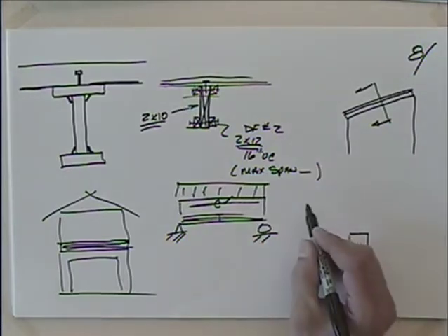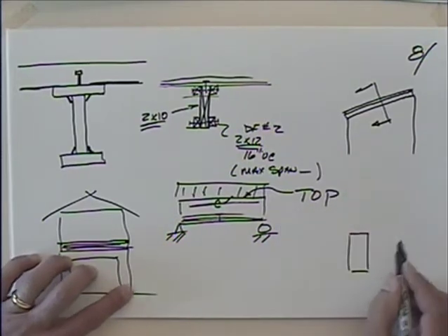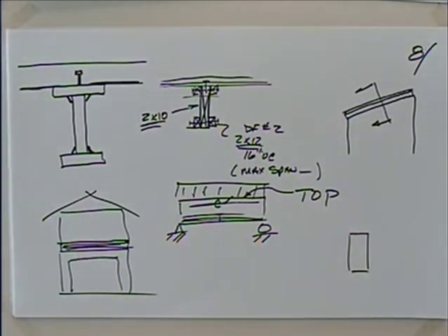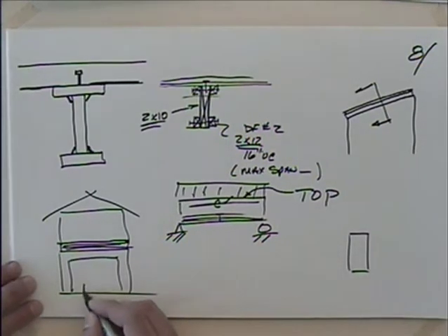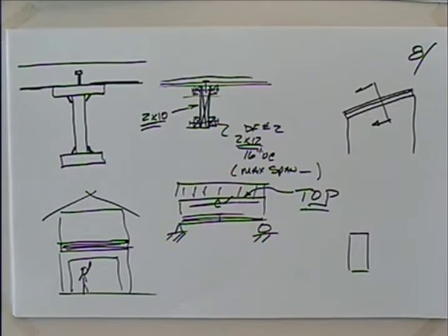The only problem is the beam clearly is marked on the top. It says TOP in great big letters, okay? Huge letters, 3 inches tall, because you don't want to put it upside down. So it's always a bad day when you walk into a structure and you look up and you see TOP. Okay? And final framing inspection is after they put the plumbing in this thing, after they put the electrical in this thing, they've got the roof on it, okay? They got the sheetrocker standing there jumping on one leg and the other, the insulator jumping on one leg and the other. They want to get this thing done.